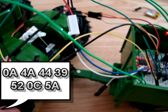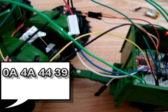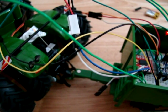Now, when we did the steering, we typed in command 02 for the steering, but I'm going to use command 0C because that is for the link servo. So I'm going to try 0C 5A for the first attempt, see what we get. So it looks like 5A hasn't moved the servo, so possibly that is the position that the servo is in.